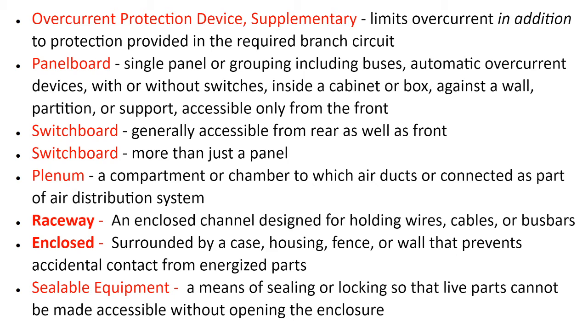Sometimes that gets you out of oversizing requirements that are unusual or specialty oversizing. So you always oversize. In specialty cases, you'll double the oversizing. If you're using way more overcurrent protection than what's code required, if you're using supplementary overcurrent protection, then that extra oversizing step may be exempted.